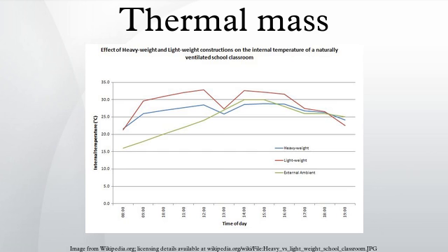Nowadays, people sometimes use earth sheltering around their homes for the same effect. In earth sheltering, the thermal mass comes not only from the walls of the building, but from the surrounding earth that is in physical contact with the building. This provides a fairly constant, moderating temperature that reduces heat flow through the adjacent wall. Rammed earth provides excellent thermal mass because of its high density, and the high specific heat capacity of the soil used in its construction. Natural rock and stone, see stone masonry.